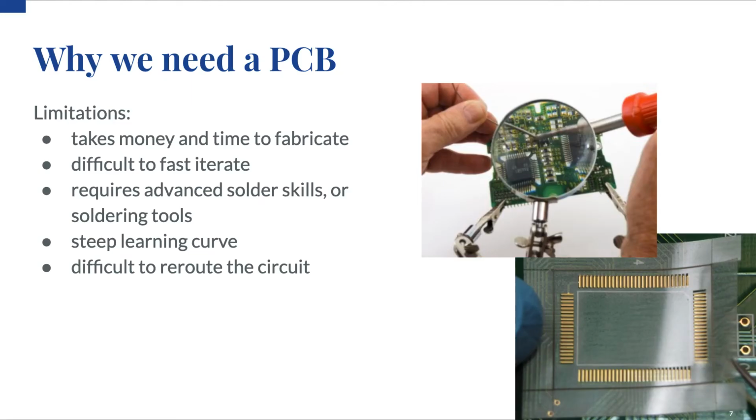The PCB also has some limitations. For example, most PCBs are customized orders, so they cost more money than perf board, and they do take some time to fabricate. And because the fabrication and shipping take time, it is more difficult to do a fast iteration on a PCB. PCBs often involve surface mount parts and small pitch parts, and they require advanced solder skills or soldering tools. Learning how to use PCB design software is not as easy as a breadboard. The learning curve is much steeper.